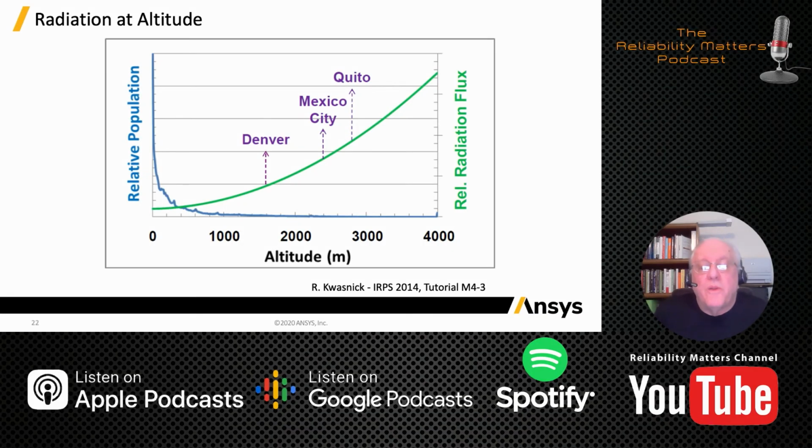So also at that reliability physics conference, there was a paper presented that showed what radiation looks like for increasing altitude. So as you can see there, you're down at sea level. Relative radiation flux densities are small. You go up higher and higher in altitude, you get more and more cosmic radiation impinging on your semiconductors. The smaller and smaller those semiconductor features are, the more susceptible they are to that ionizing radiation.